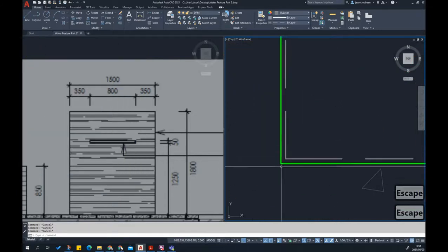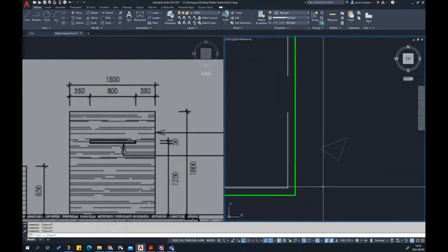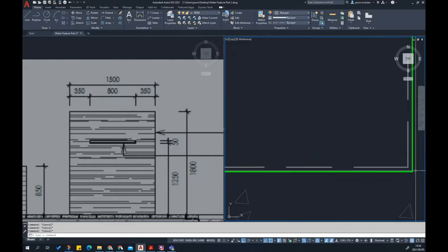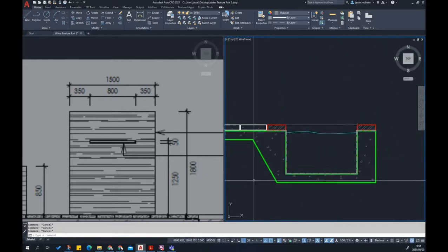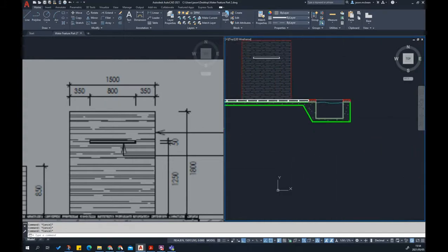Just one thing to bear in mind, concrete can never be cast perfectly square, so they put in a filler piece. It's because if big pieces of aggregate stick, it breaks out these corners, so just bear that in mind. I can show you how to fix it very quickly, but for what we're doing, just bear that in mind in future. You can never have a perfect corner in concrete.